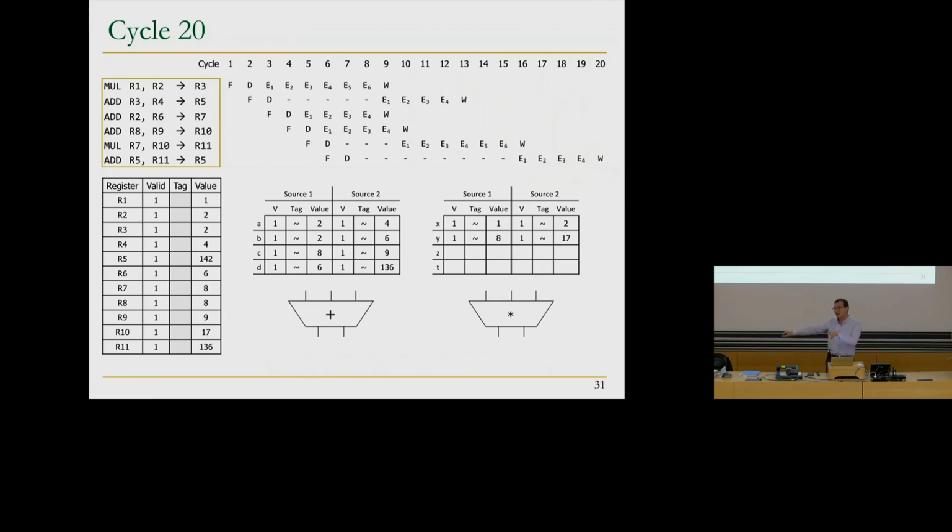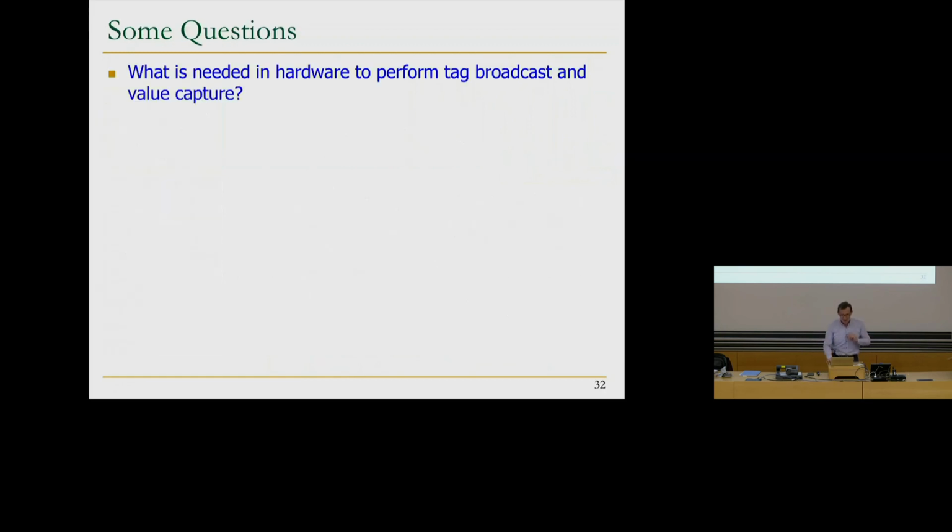But you cannot take an instruction that's after the add and rename it, because that will break all of the linking that we do in terms of renaming, right? So renaming is all in sequential order, so that you can link the instructions. You cannot do out-of-order renaming. I mean, you could, but it complicates the system a lot, actually, and people don't do it.